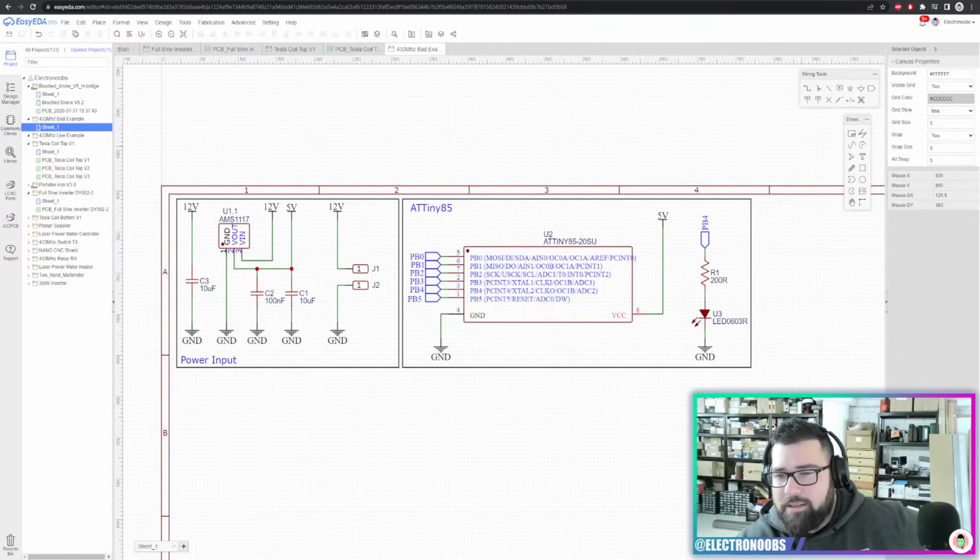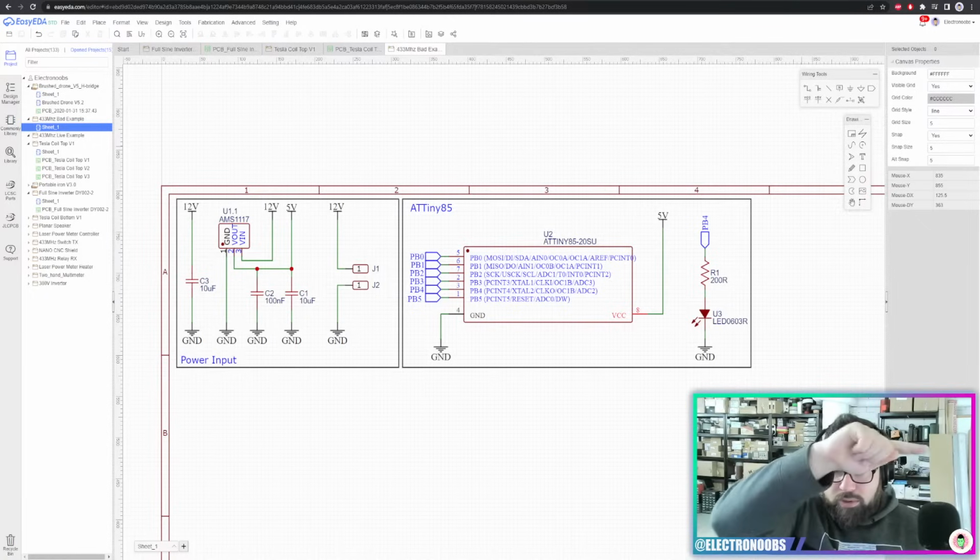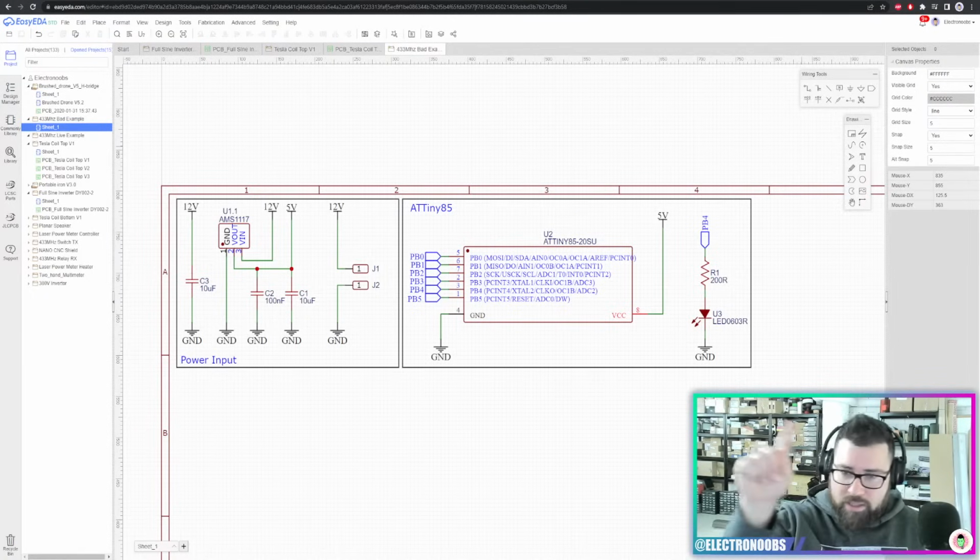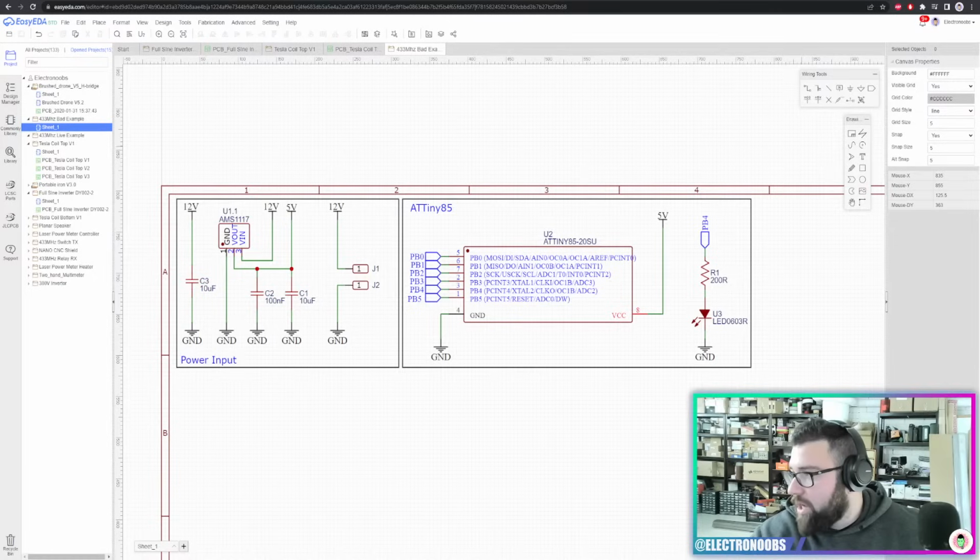In this case, this is using AC input, and the shunt was placed between the grounds because when measuring the input current in a loop, measuring on this side or on this side is the same, because the input current is the same as the output current. So the shunt is used to measure current, not as a safety feature. So if you want a safety feature, just add a fuse, and yes, it is a lot better to place it on the top side of the circuit.